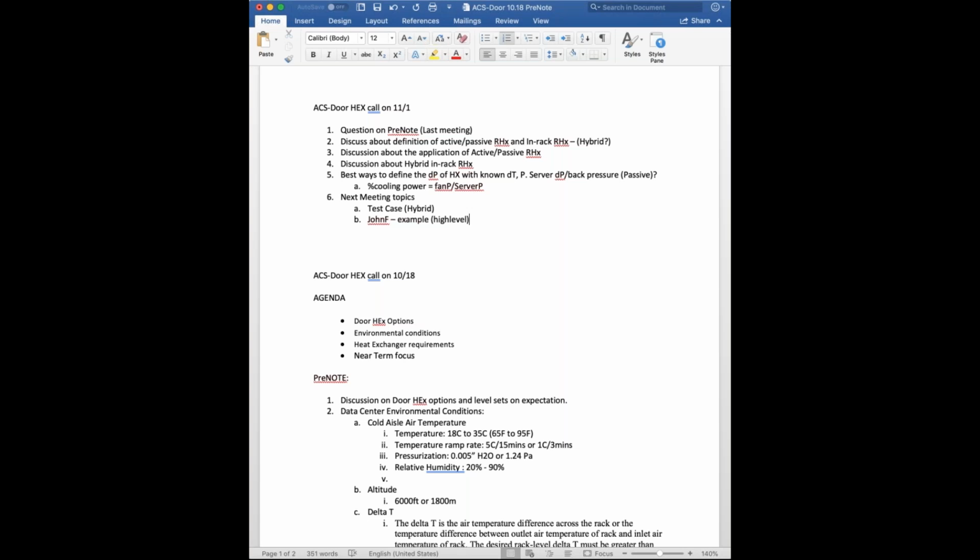And for a cooling coil, the slower the air is, the better your approach will be. So from a cooling point of view, the less flow, the better. But that's a delta T thing again. So it's all hanging together. What is your supply air? What's the delta T over the IT equipment? And which power is needed, and that will determine what the heat dissipation will be and what the delta T will be over the coil. Yeah, it's kind of a balancing act, right? Because if you lower the airflow, then your delta T goes down. But if you lower the airflow, your capacity also goes down. So you have to balance that.